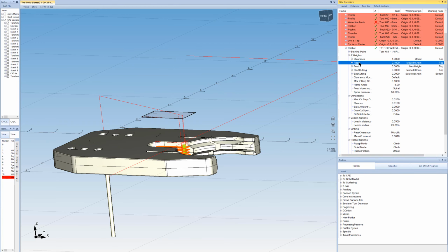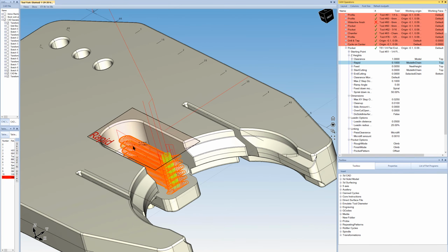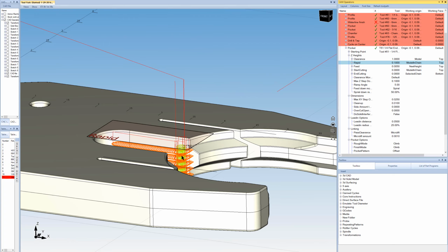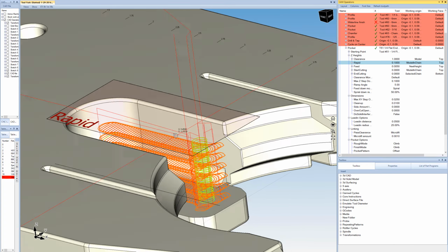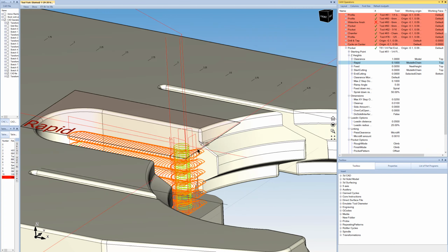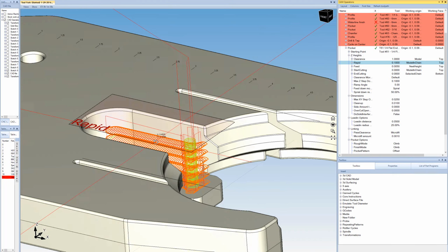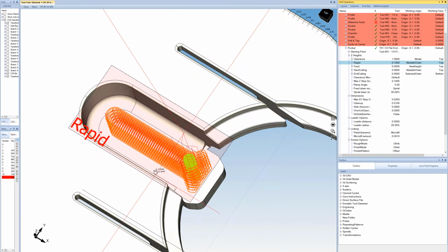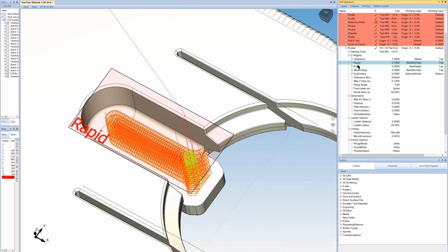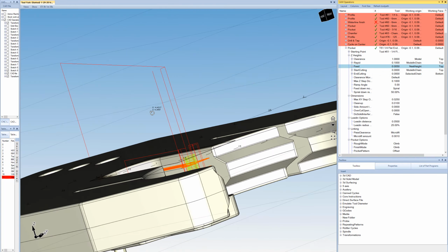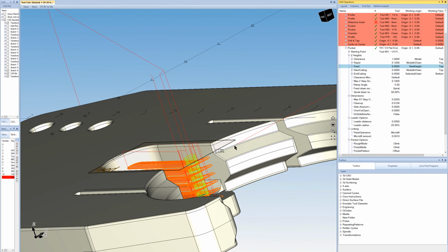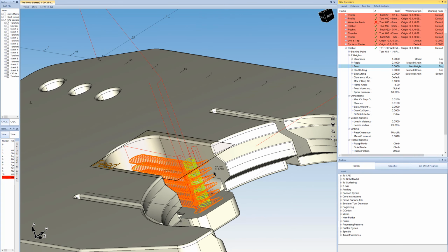Okay, our rapid plane is down lower typically, and this is the plane that it's going to use kind of internally inside of the pocket routine when it has to go up and then transition over to continue, say, a different area of the pocket. Okay, so that's kind of in the middle of the actual pocketing routine. Our feed plane is how high it's going to go. Is our height plane for when it transitions from our rapid move to our cutting feed rate.